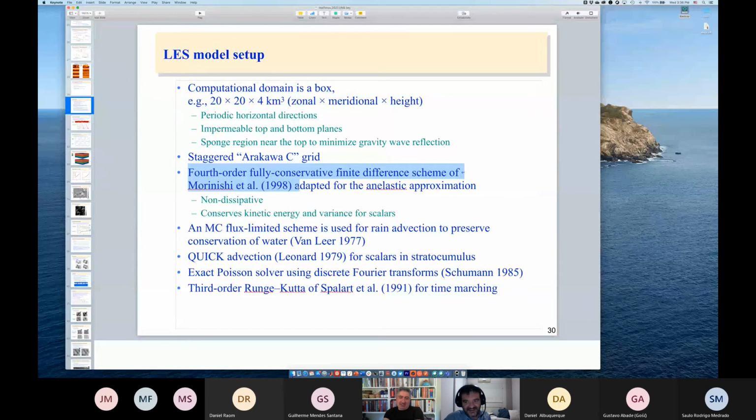If you're doing neutrally stratified turbulence, this is fine. But if you're getting into stratified situations where the Richardson number is too high, and you're not supposed to have any mixing from your SGS model, these models are unaware of the Richardson number, so you might get into situations where this is mixing too much. This model here, like the Smagorinsky, if the flow is too stratified, will shut off. It will produce an SGS tensor that is just zero. It will say, I see no turbulence here, it's just waves, so I'm not going to do any mixing.